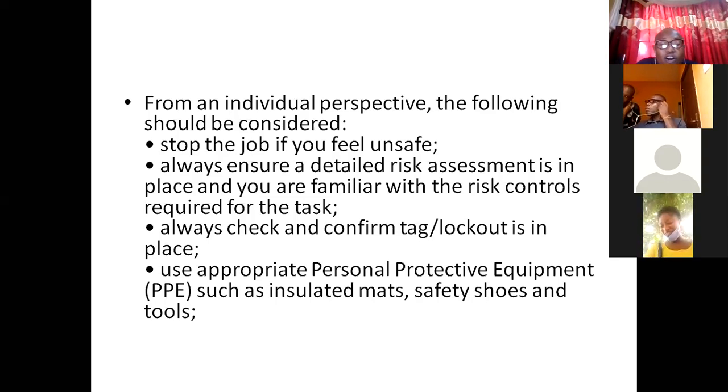Always check and confirm tag out and lock out in every place. Always ensure that you check and confirm tag out and lock out before you do anything, because you don't know whether somebody else is already working and has tagged the place out, and you now go and switch it on. You expose the person to hazard and that person may die.